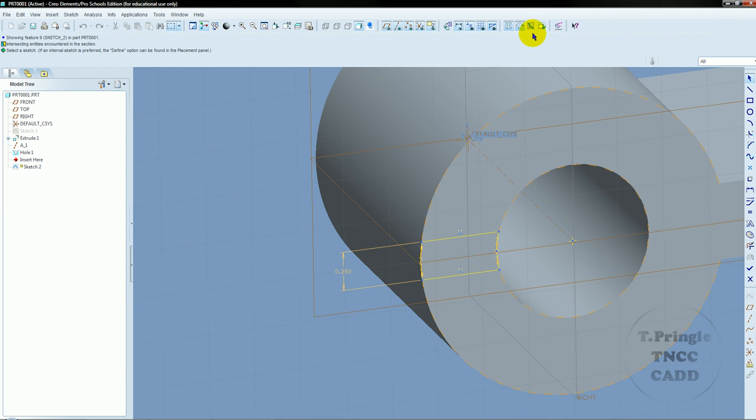So another tool that we have is this button right here, which will show any overlapping geometry. When I click on it, it pretty much highlights the whole thing, but I'm pretty sure it's these in here because I drew these lines, so it's probably these arcs. So I'm going to go to delete segment, and I'm going to get rid of this and this. Okay, it wasn't on that side, it was on this side.